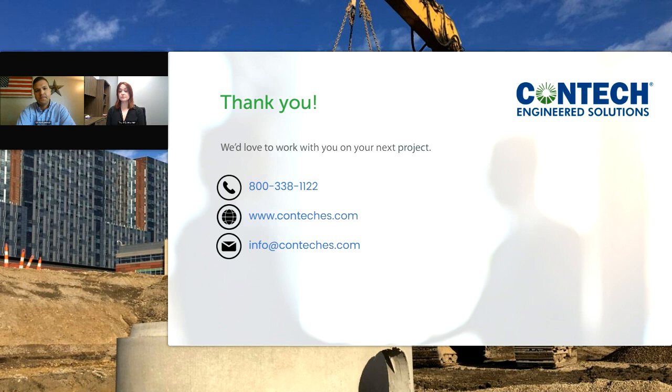Thank you, Marko. Are any of your HDS systems approved for full trash capture? Yes. Our CDS separator, one of the most common and regularly used separators nationwide, is rated for 100% trash capture and retention. And our debris separating baffle box, the DSBB, is also rated. We typically follow the California State Water Board, and they set the trash capture requirements.